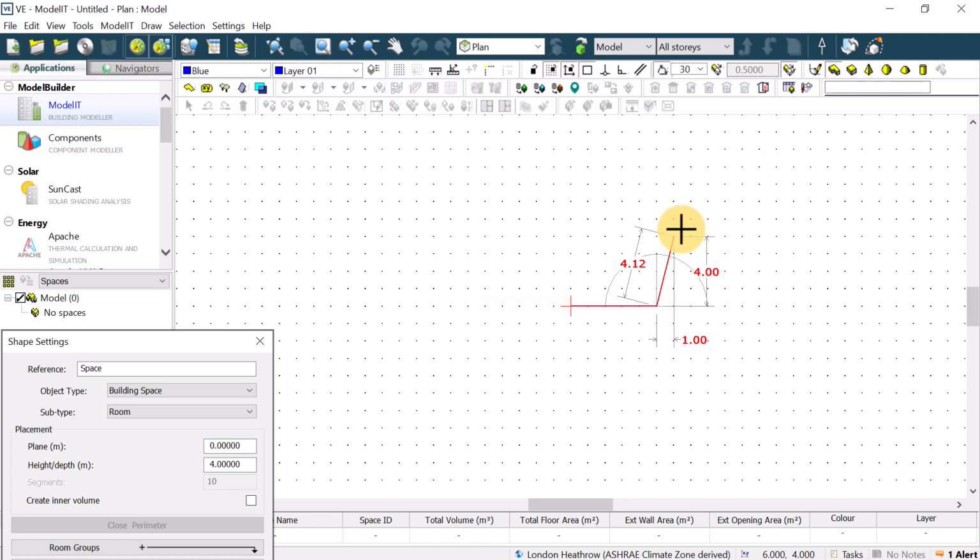If we want to draw a vertical line, we can, for example, type dx equals 0, to have no change in the x-axis, and then type in the vertical distance, let's say 3, and hit return. This will draw a line that goes 3 units straight up the screen. Here, if we had typed -3 instead, the line would have gone down the screen.